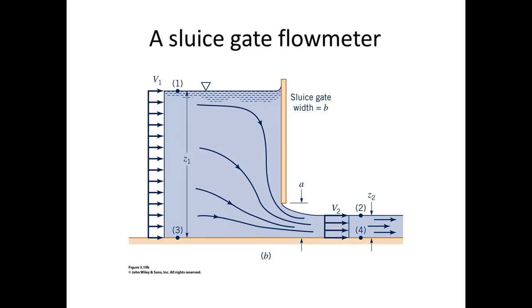Well, the flow itself is pretty slow. You could measure the velocity straight away, but it's not so easy to do. A slow velocity takes a long time to measure. A good way to get a quick measure of that velocity is to raise the gate. Look down here, you see a vena contracta. The water jet comes out there and goes to a velocity V2, and again, using a combination of Bernoulli and continuity of flow, you can solve for V2.